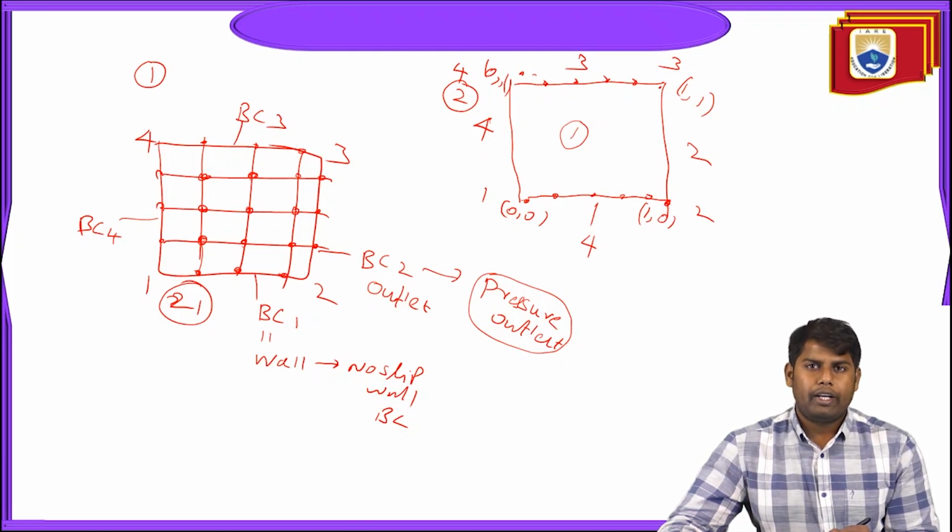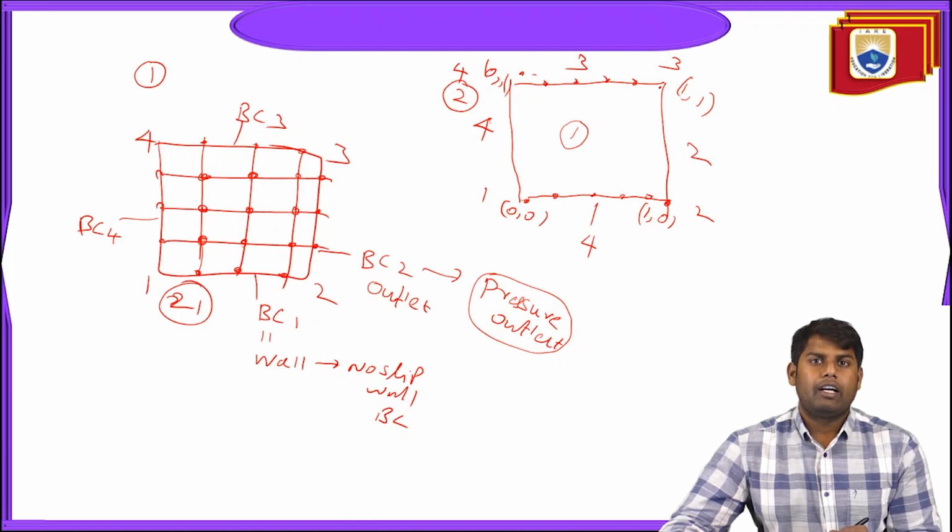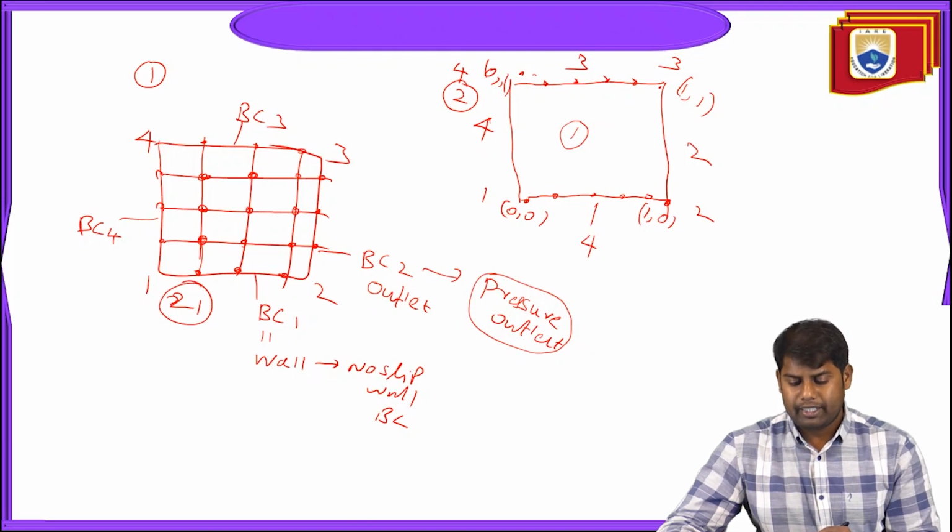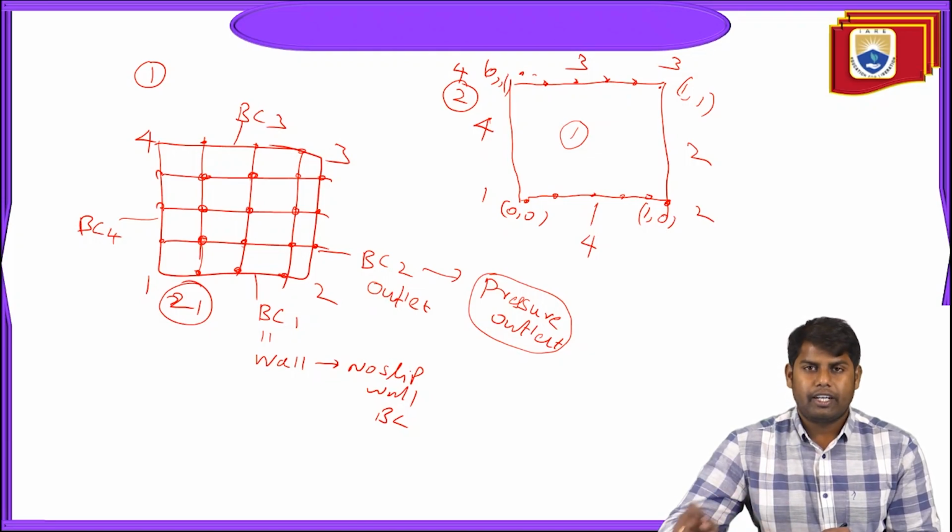The choice of the grid points is basically coming out of the physics of the fluid. So what you need to capture and what physics we need to see, this is very, very important. Therefore, initially when you perform a simulation, the most important thing is to decide what should be the minimum number of grid points to study the flow behavior in the numerical simulation. Okay.